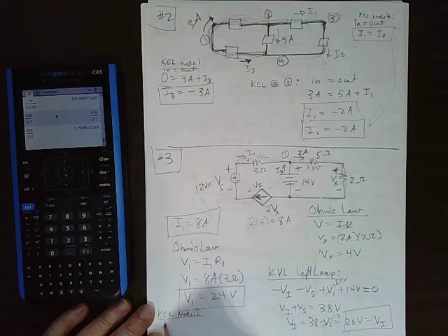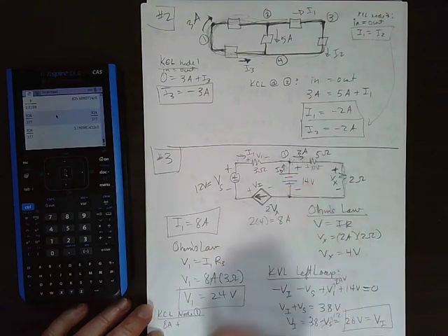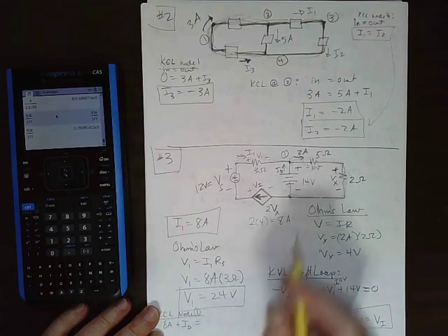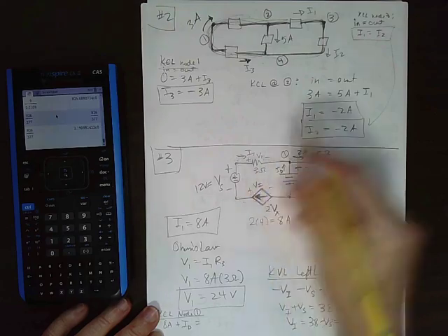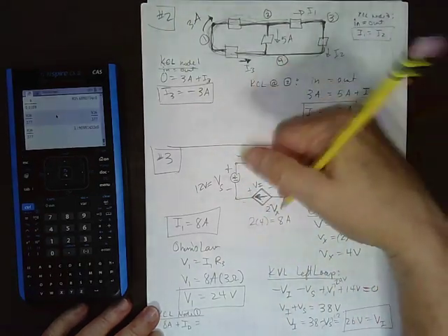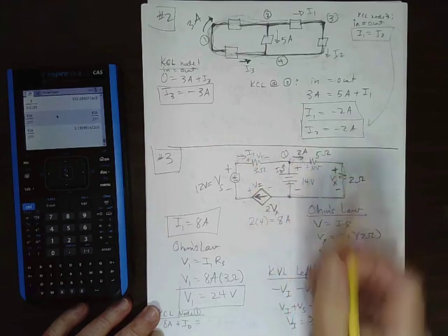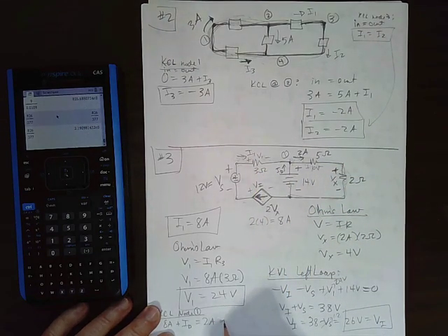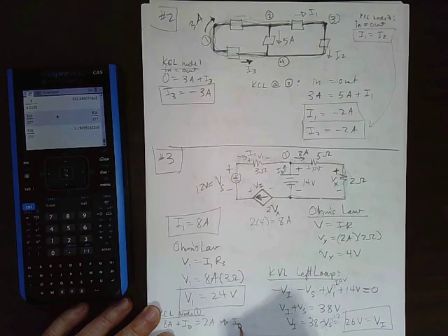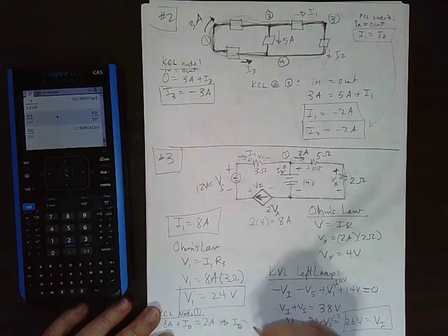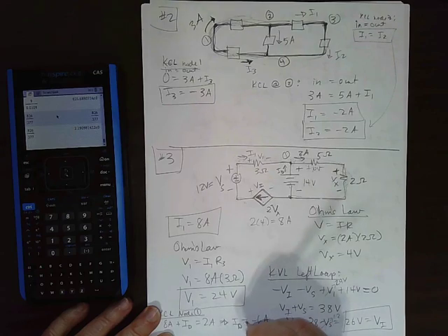I1 is 8 amps. And we've got ID going in, what we're looking for. And that's all that comes in. If we have 4 or 5 branches, we could have 4 or 5 currents coming in or out. So we have just these two coming in, and what we got out is 2 amps. All right, so ID equals, okay, negative 6 amps.